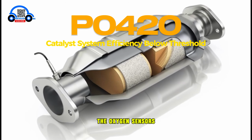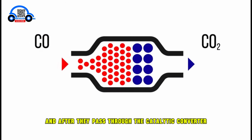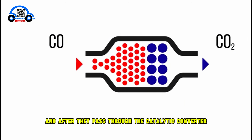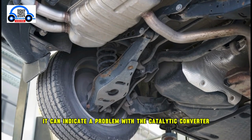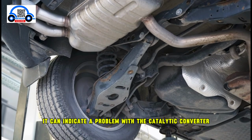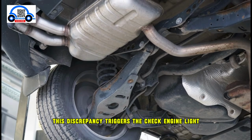The oxygen sensors monitor the levels of oxygen in the exhaust gases before and after they pass through the catalytic converter. If the readings from these sensors are outside the normal range, it can indicate a problem with the catalytic converter or the sensors themselves. This discrepancy triggers the check engine light.